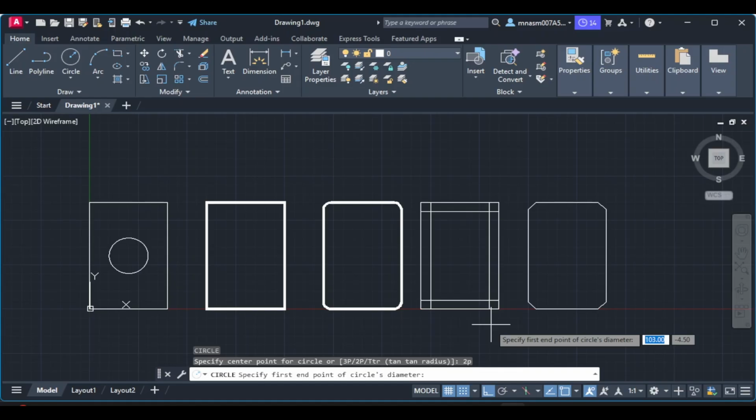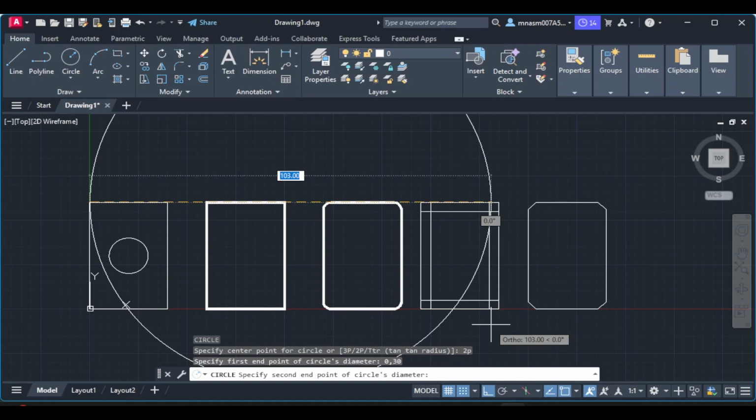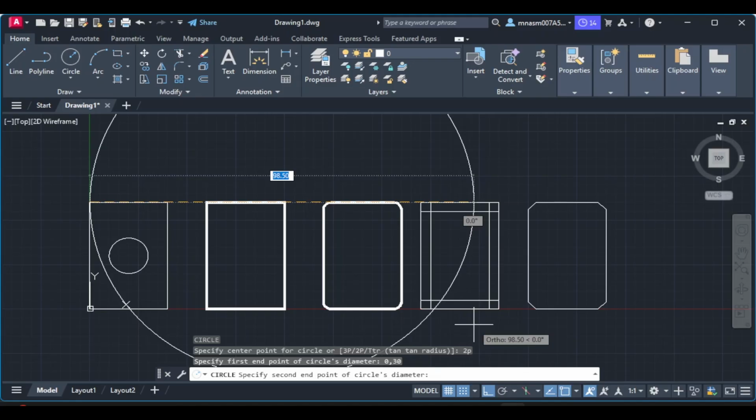You see, one important thing is that it is taking the dimensions with the cursor. So it is relative coordinates, not the absolute coordinates. So I have to specify the point from the last corner point that I used. Relative to the last corner point, the other corner point, the top right corner of the first rectangle, will be 20 comma 0. So I will type 20 comma 0 because it is the relative coordinate method, and then hit enter. So the circle will be drawn.